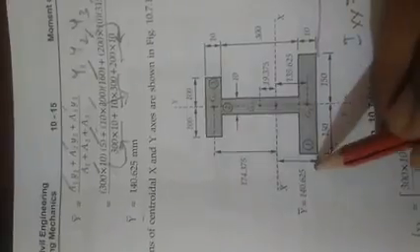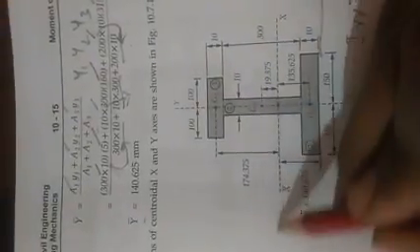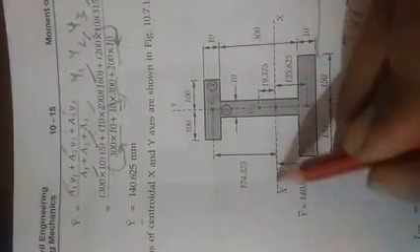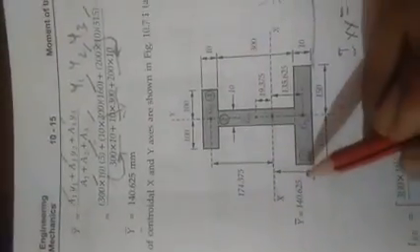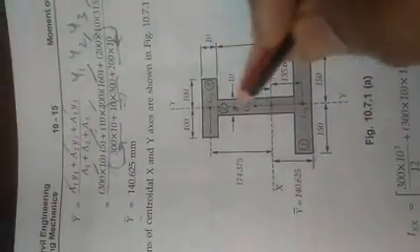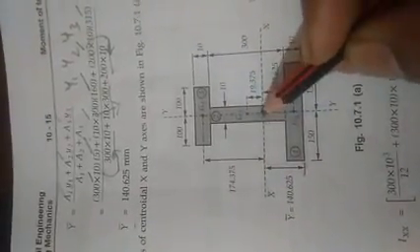So now you got the answer as y dash equal to 140.625. So what is this? 140.625 is the centroid. Exactly, the centroid will lie at this distance from the reference axis, at 140.625 mm. You know that in the x-axis, it will lie here. So on this line only you will get the centroid.